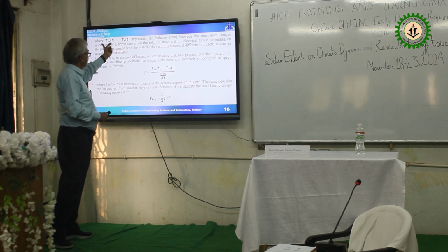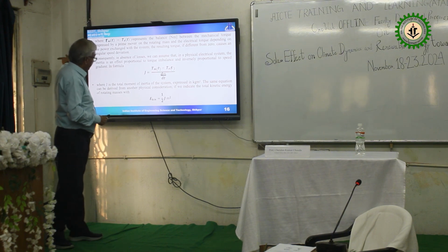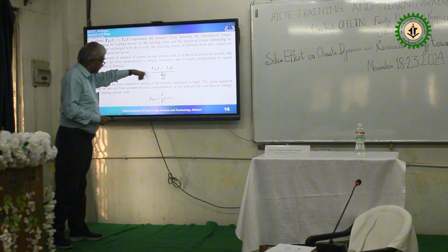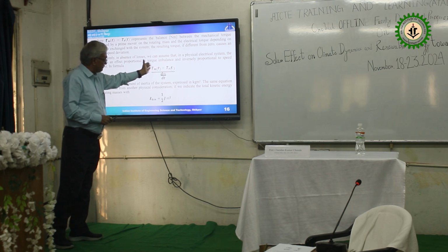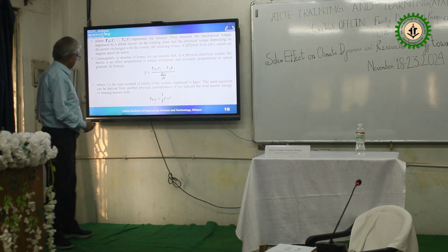M and E mean the mechanical and electrical. And from here, from the basic definition that we wrote, I'm omitting (t) intentionally, but it is a time dependent function. Tm minus Te divided by dω/dt is equal to J.